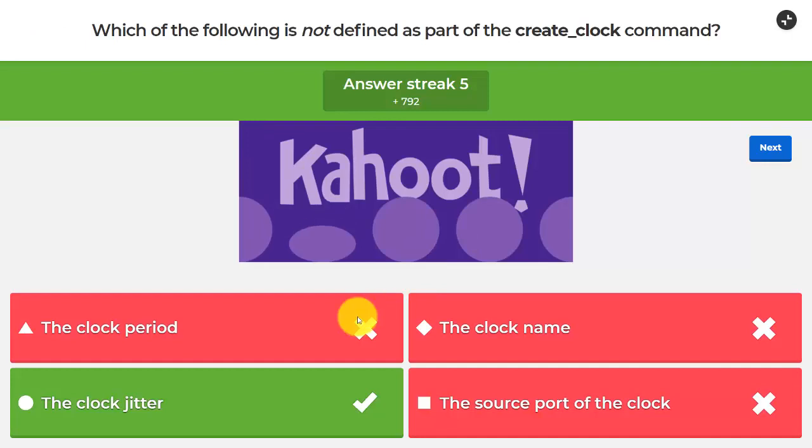So going back there, we do not define clock jitter in that command. Obviously, everything I showed here, you have to do a man or help on these different SDC commands or look into the documentation. There are many more options, but as far as I know, clock jitter cannot be defined in the create_clock command, and even if it can, it's not something that's used. It's defined separately, as we'll see in a second.